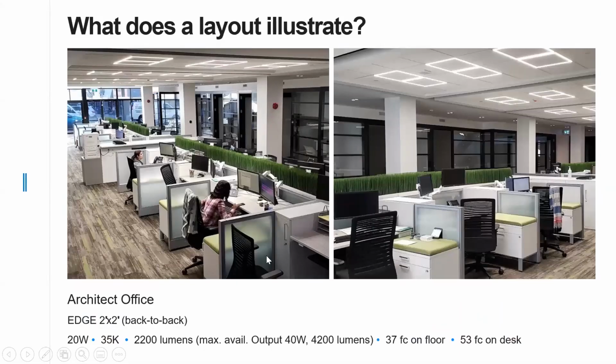But what is a layout going to tell us? Well, it's going to tell us the most important information and the reason for which we're doing a basic layout, and that is what are we going to get? So in this case, we were using an edge with a 20 watt output at 3500 Kelvin, which delivers 2200 lumens. We could have delivered 4200 lumens, but we chose 20 because we had specific targets.